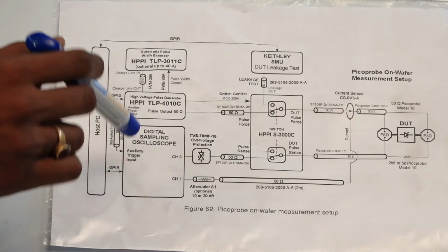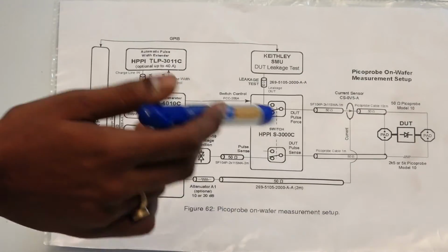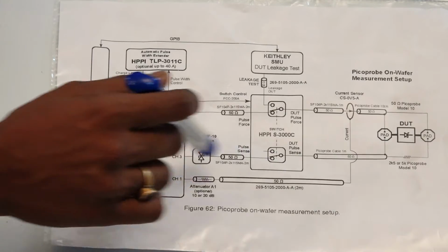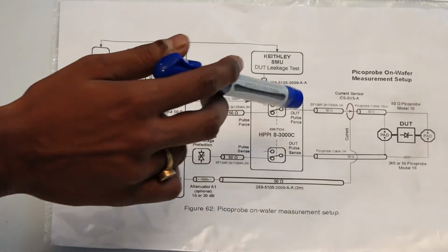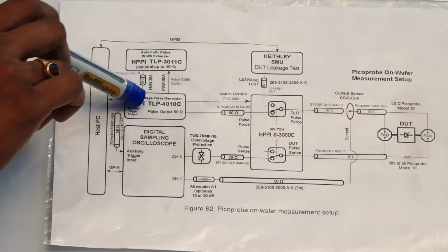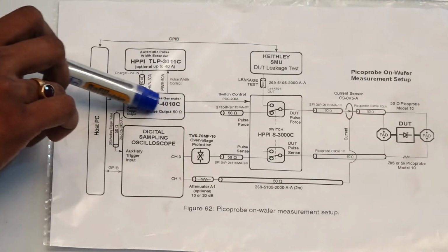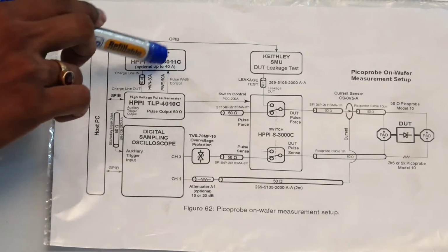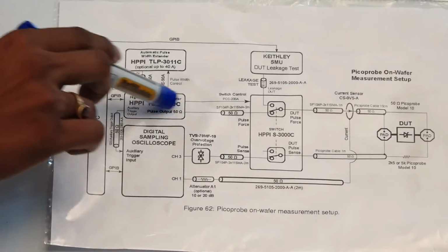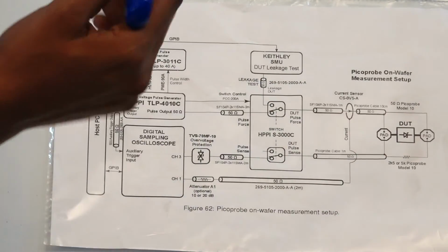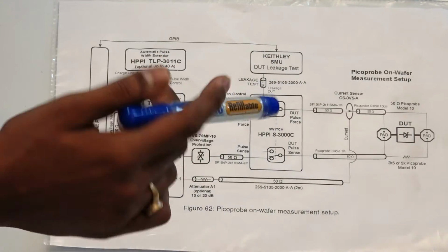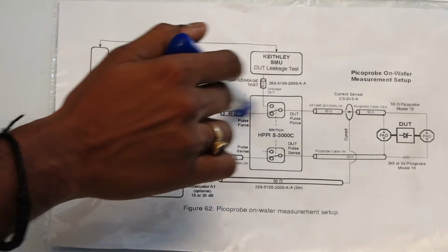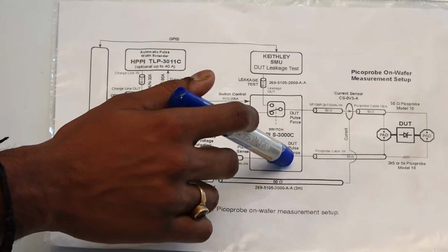So some of the major components involved in the whole setup, as you can see, are these: generator and the pulse width extenders, oscilloscope, this switch here. Now this switch becomes important because this pulse that you're applying is a 100 nanosecond or even lower pulse. The lowest that we can go is a few nanoseconds, 1 nanosecond. And this switch has to switch as fast as possible, because it also has to alternate between these measurements. So this switch becomes very important.